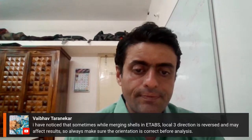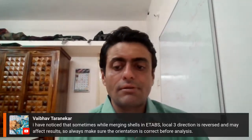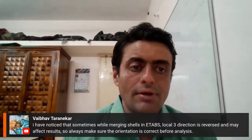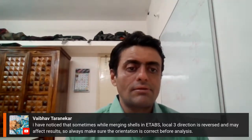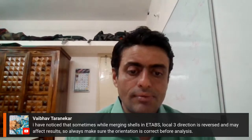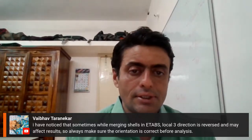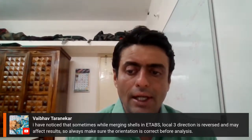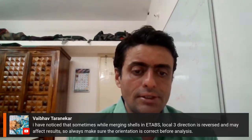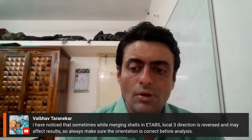So his point is that the local 3 is reversed and may affect results. Oh, okay, it's not a question, it is an observation. So, always make sure that the orientation is correct before analysis. Yeah, very important. You should always try to observe before you apply the loads and before you run your analysis. Ensure that all these shell elements and line elements have the local axis properly oriented. This is more important for the shell elements, not as much for the frame elements. But yes, he has made a good observation over here.